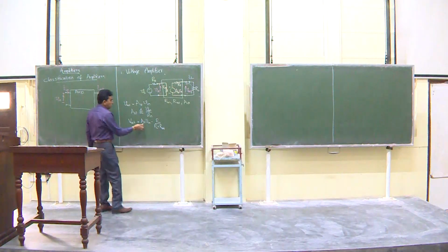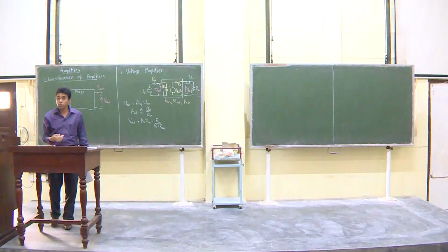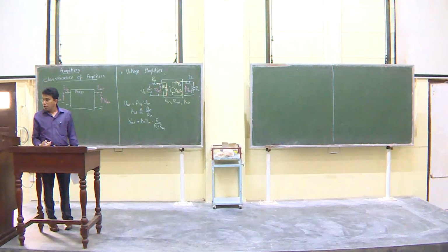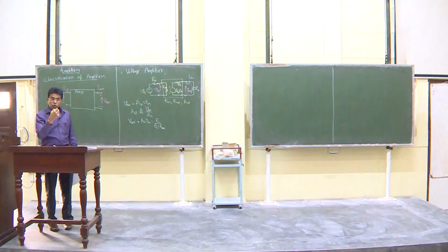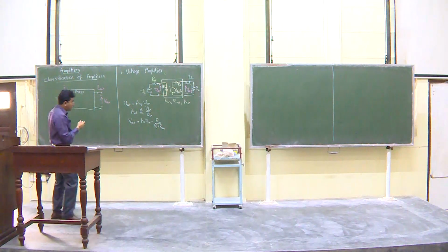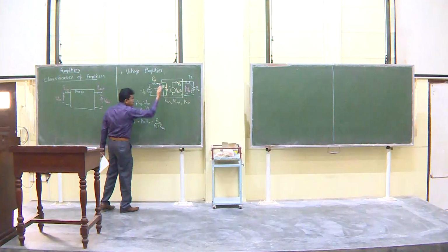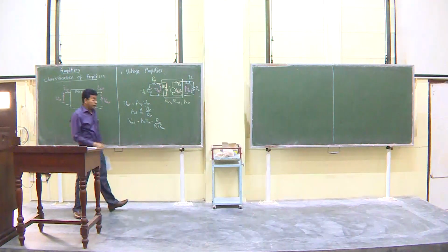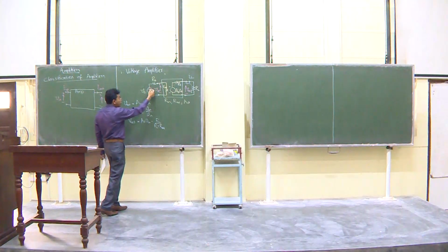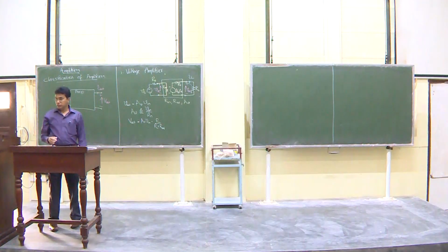Now, our source is what I want to amplify. This can be my microphone. What I want is the microphone signal to be amplified by a certain amount. But what happens here? This is V in. As soon as you connect it to this black box, the amplifier, it has an input impedance. Again, just like that, you have a voltage source in series with two series resistors.